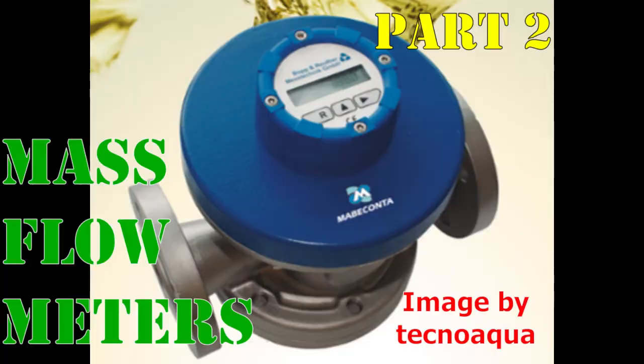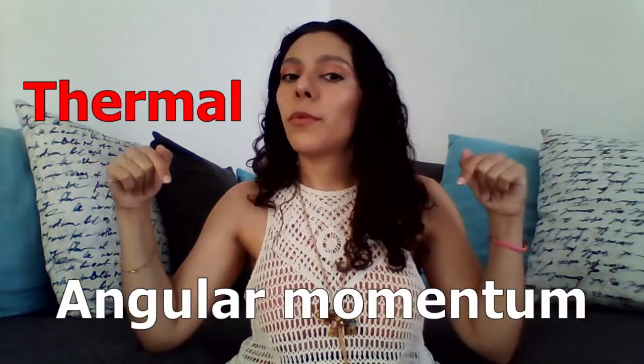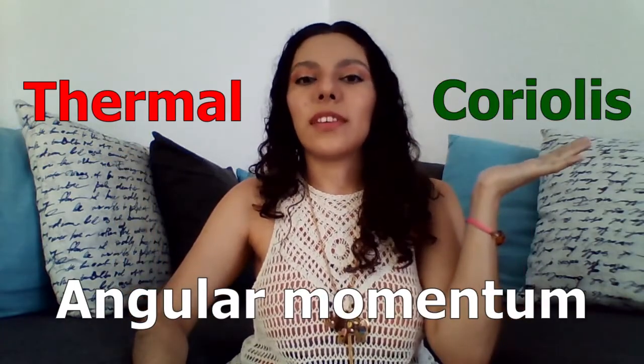Welcome to my channel. Today I'm gonna talk about mass flow measurement. Although volumetric flow methods are commonly used in industry, it is sometimes required to measure mass flow, either by compensating for pressure, temperature or density, or by taking advantage of measurable characteristics of the mass with basic direct measurement systems, which are thermal, angular momentum, and Coriolis instruments.